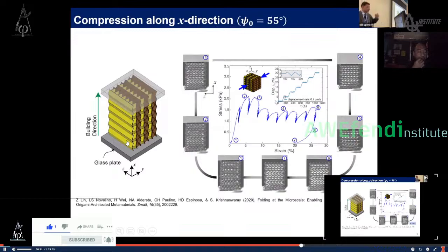This material is viscoelastic, then we modulate load, as you can see here. And then if we test in the X direction, you can see it's more or less an elastic material that has a plateau, will flow. And what is very interesting on this, if you look at the numbers here, we start here, and then you can see that around 5, for example, there is a tremendous deformation, but as we remove the deformation, as we unload the specimen, it recovers almost the original configuration.